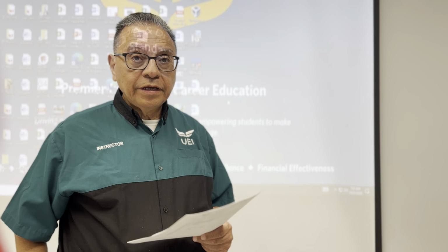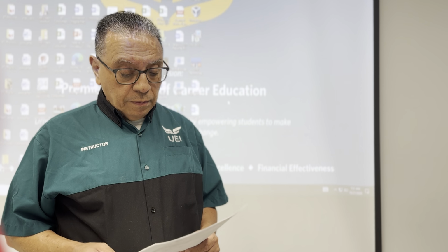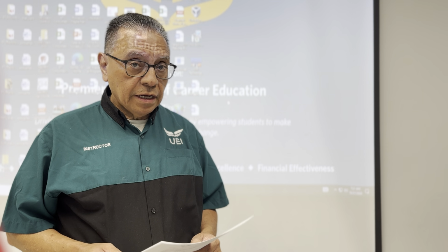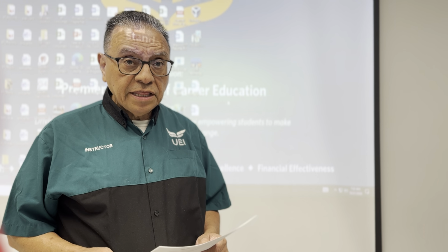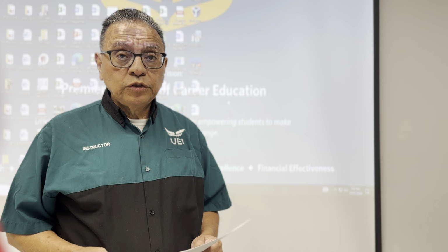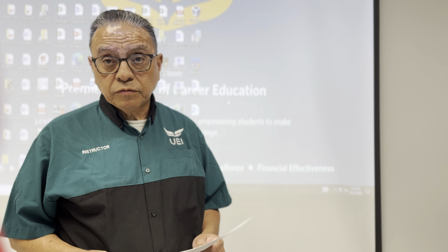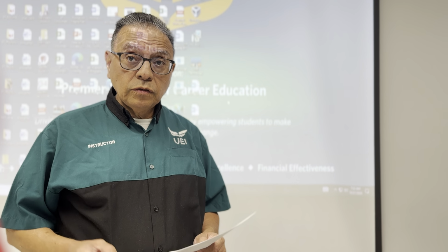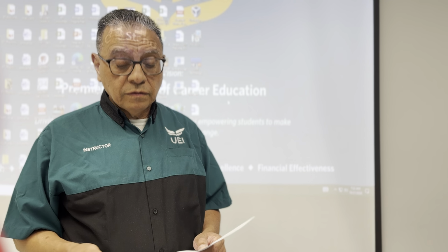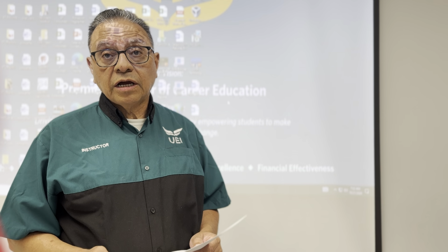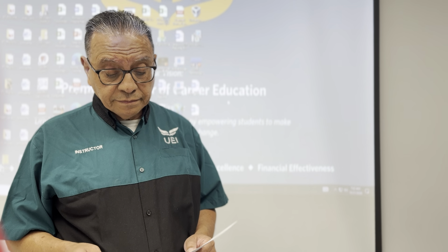Good morning, class. Today we are going to continue with the PLC programming. I will be creating a short program to simulate a non-retentive latch, similar to using a start-stop push button station to start an electrical motor, and this process will also affect the startup of a second device, or a second electrical motor, or a second set of lighting system.